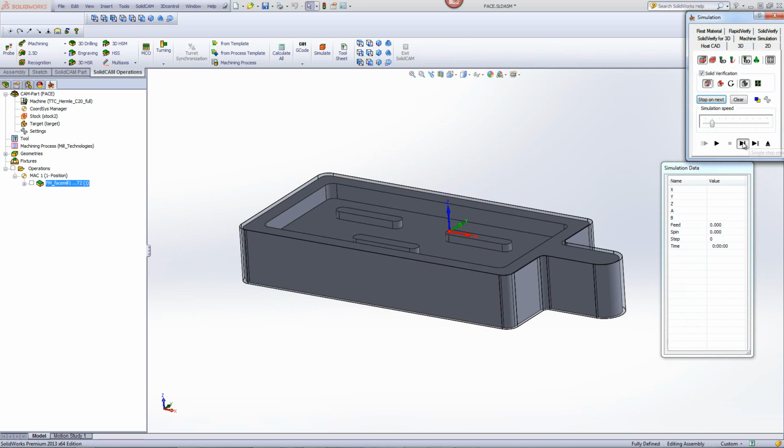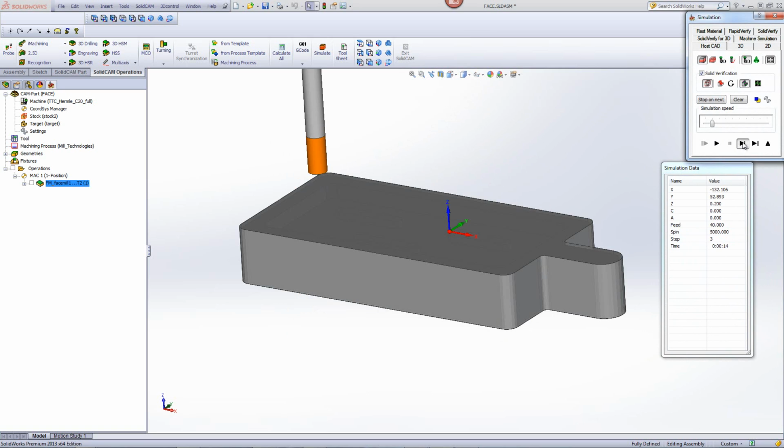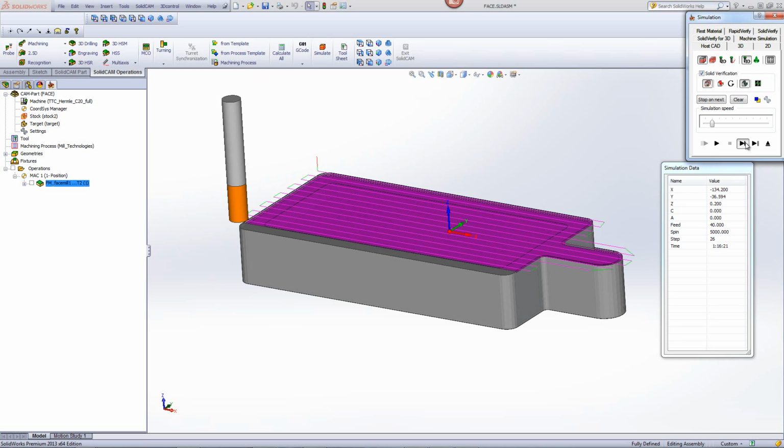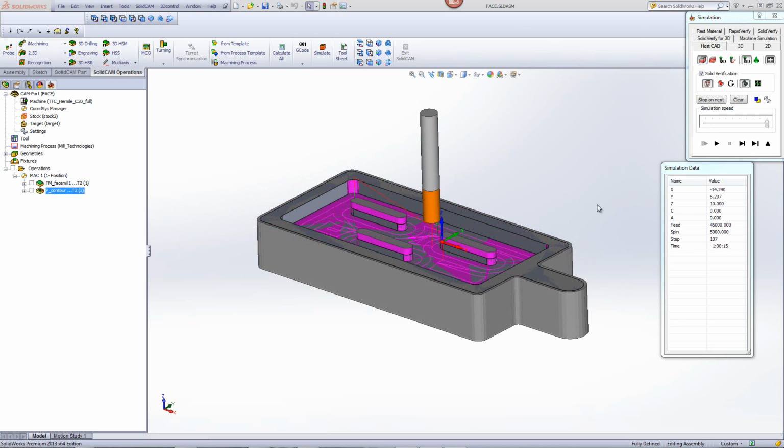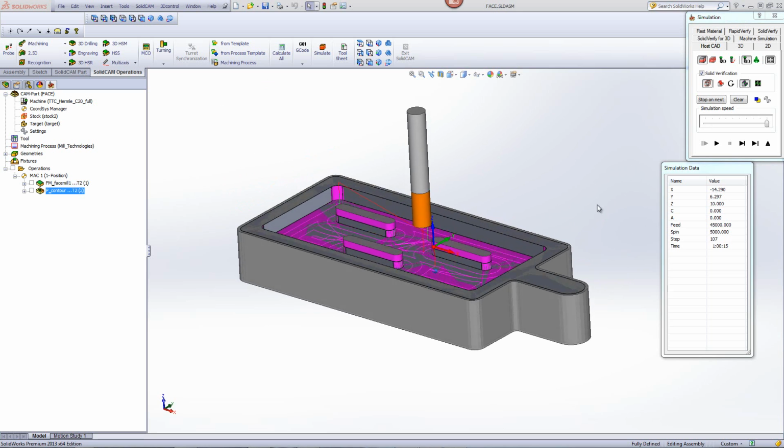Our first step goes across, and you can see that our Z level is 0.2 millimeters, in other words, offset from the actual zero surface that we want to go down to. It'll go across, and when it finishes the step, since I had marked that I also want to do finish, it'll go back to its zero level as shown over here, finishing off the entire part until the very end.